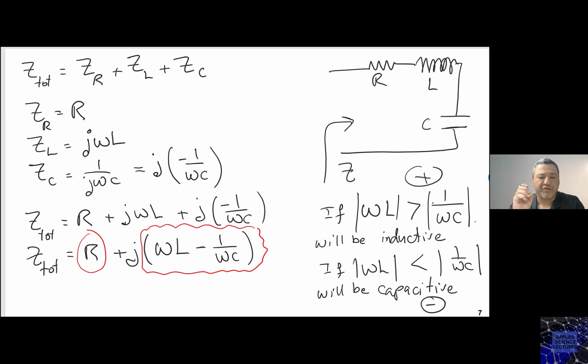We shrink the dimensions in order to get rid of those parasitics, because sometimes you can have a capacitor whose limiting factor is the frequency. So you cannot do anything about it. It has a self resonance. You cannot use it as a capacitor beyond this frequency, because it will change from a capacitor into an inductor. Sure, yes, go ahead.